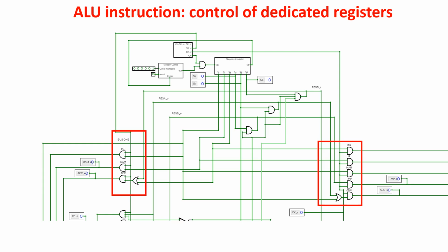The pulses are created through 2-input AND gates, having as first input the clock E or the clock S, and as second input the right step of the stepper, which makes sure the pulses are created at the right time. To understand the wire connections, see the proper simulation videos in the playlist, in particular the fetch simulation and